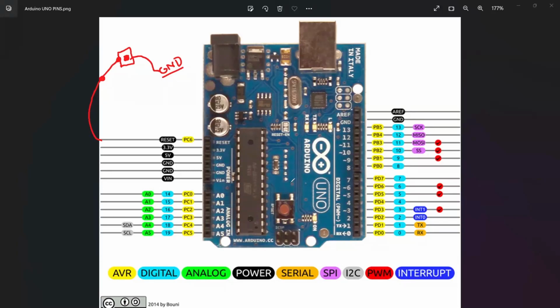Otherwise, you can utilize the reset button mounted on the board, if the structure is not that closed, or you can access the button from outside the box or structure. Either way, you can use the reset pin to make one connection to the push button and place the push button outside the body of the robotics structure, so that it will work the same way.